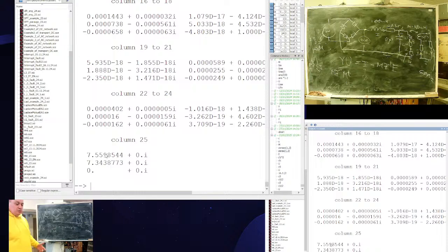I started looking for the small difference: diodes have a direct voltage drop. If I have 10 volts at input of rectifier, I need to deduct 0.6 volts for each diode. That means 1.2. There was the difference. I forgot to deduct voltage drop. Diodes have their own voltage drop. Yes, now it's. Where is the chart?